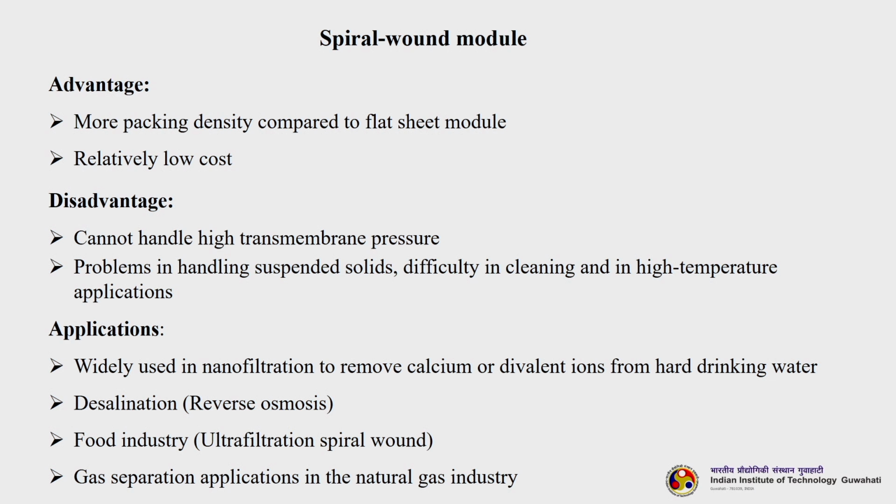Since they are rolled and glued to each other, cleaning is a big problem, and they cannot be used for high temperature applications also, because it happens many times in process industries that the streams coming out of the various process units are at elevated temperature and need to be separated or purified for certain targeted separation. So, in that case the feed will be at higher or elevated temperature.